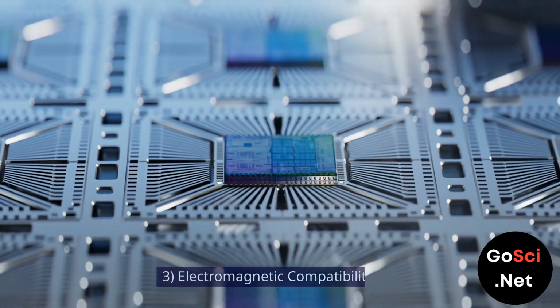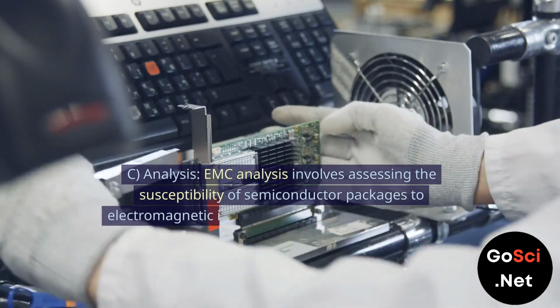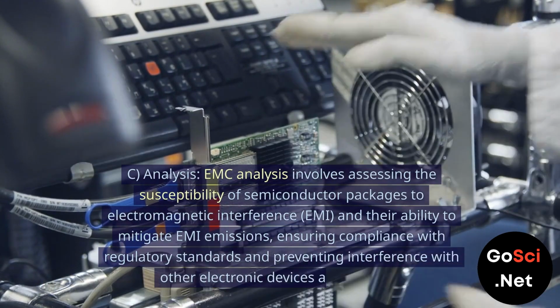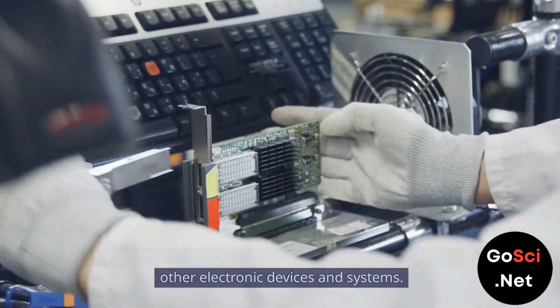3. Electromagnetic compatibility (EMC) analysis. EMC analysis involves assessing the susceptibility of semiconductor packages to electromagnetic interference (EMI) and their ability to mitigate EMI emissions, ensuring compliance with regulatory standards and preventing interference with other electronic devices and systems.